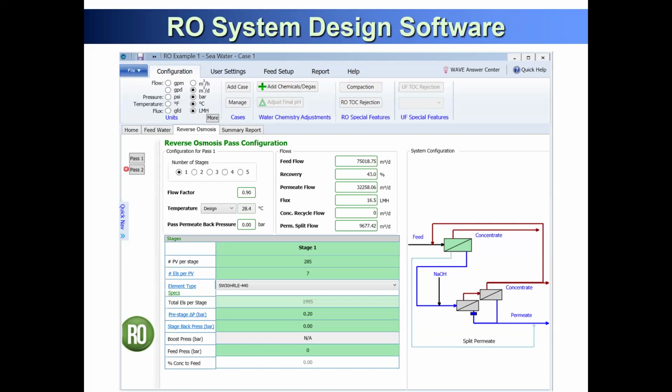So you consider that after 1 year, we decreased around 10% of the overall permeate flux, so you put 0.9 in this case. Your membrane lifetime is 5 years in general, so you design for the average, let's say 5 years. You may have membrane fouling at 2.5 years with around a 20% decrease, right? So a 20% decrease means the flow factor is 0.8, right?